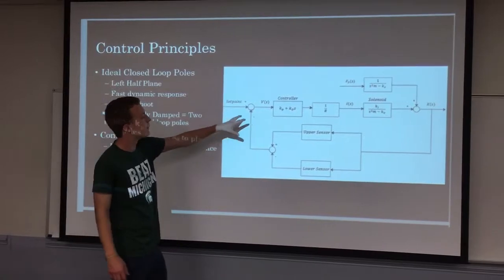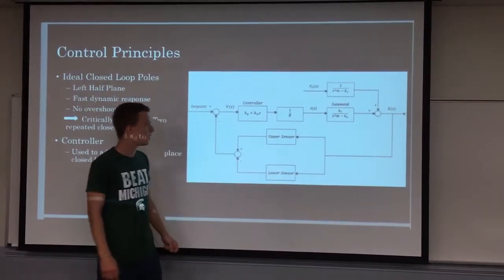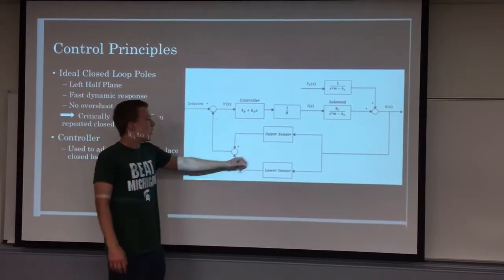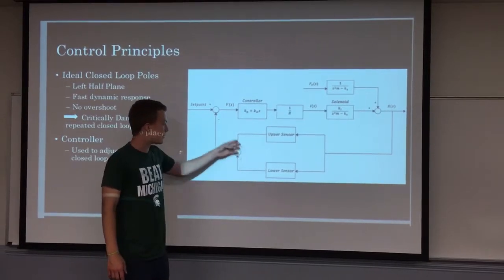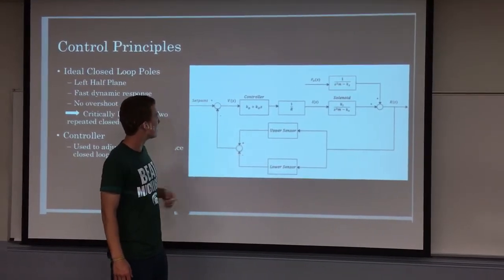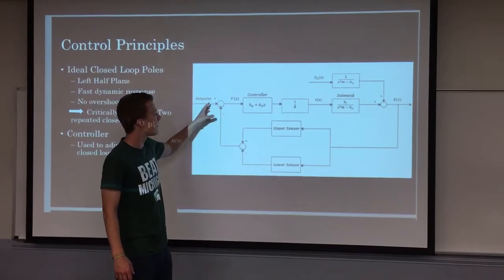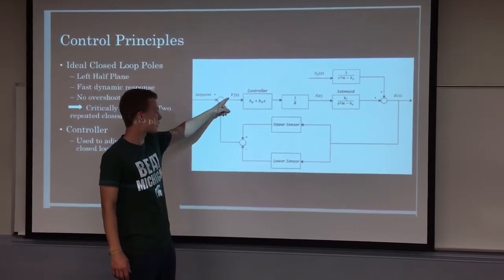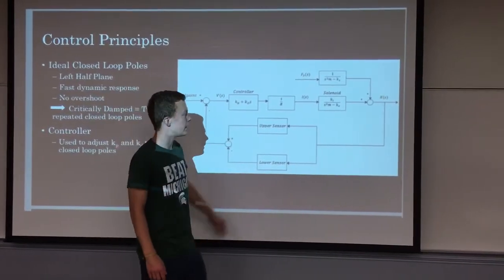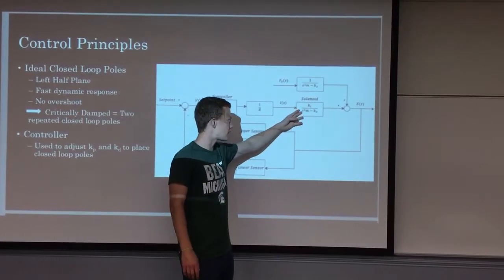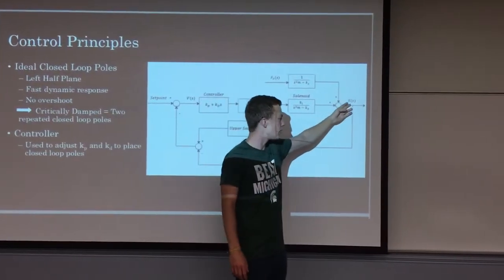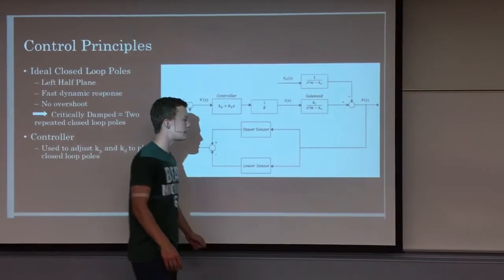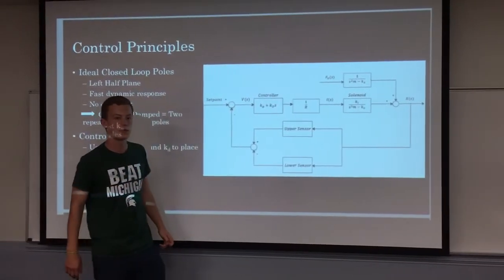This is how we thought our process could look like. We have two sensors down here that we subtract from each other, and a set point that we both feed the error function into the controller and have the solenoid transfer function, which then leads to the actual distance of the ball from the solenoid.